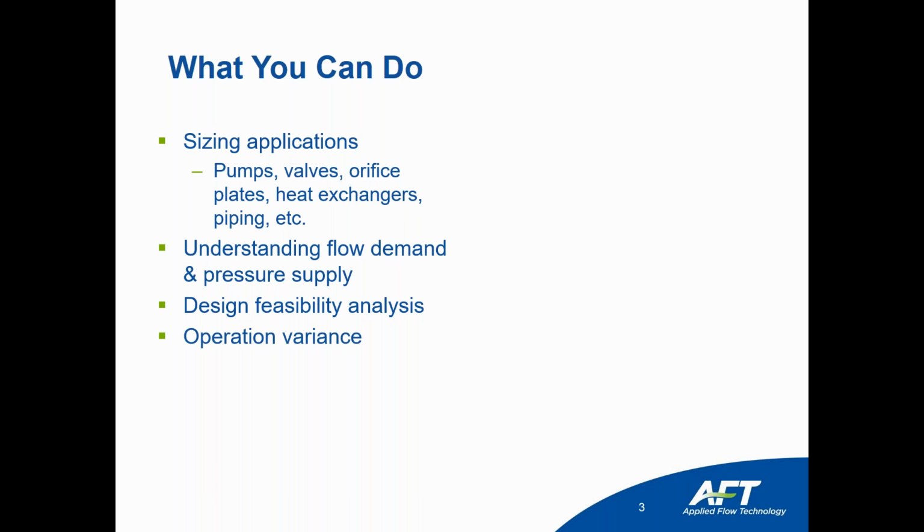And that's done with our Scenario Manager, which is one of the most powerful features of the software. You can model any variety of cases that you want within a single model and change any parameter that you like. You're not limited to just changing boundary conditions or turning things on and off. You can change any input parameter. And there's intelligence built in so that if you make a change at a parent scenario, it will pass those changes down to the child scenarios, so you only need to make the change once. So lots of efficiency is built into the software.